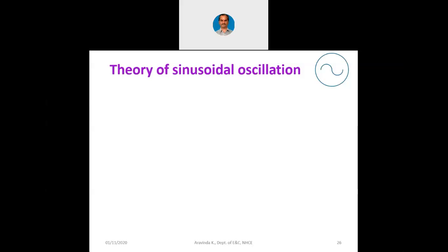That way, digital and analog can be clubbed together. For example, the oscillator is completely analog. Now, the oscillator can be connected to a particular timing circuit using digital circuits, and the oscillator's output can come out to the switch, which is a digital circuit. Out of the switch, now the signal will come as we require it, like a shorter beep or a longer beep, beep with time duration in between, beep with gaps in between. Maybe gaps also can be programmed as larger gaps or smaller gaps. All that is possible. That is called a hybrid circuit then. Means analog and digital together, that is a hybrid circuit.